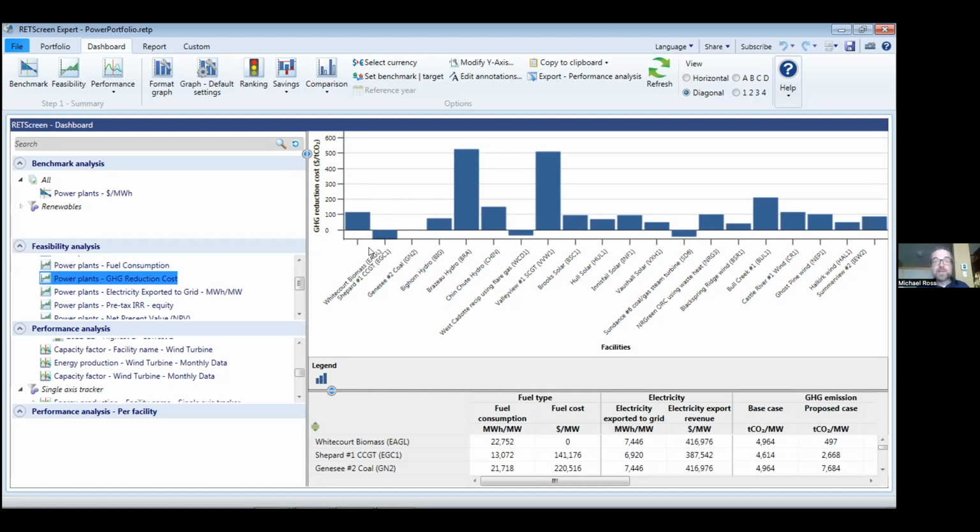And that includes coal-fired generation. So if you're comparing combined cycle, highly efficient gas generation with a grid that contains a fair bit of coal, yeah, the emissions are going to be lower with your highly efficient gas generation. So it's going to generate emissions reductions compared with the existing grid, which contains coal. And that's why we see an attractive GHG emissions reduction cost here, negative cost for GHG emissions reductions.